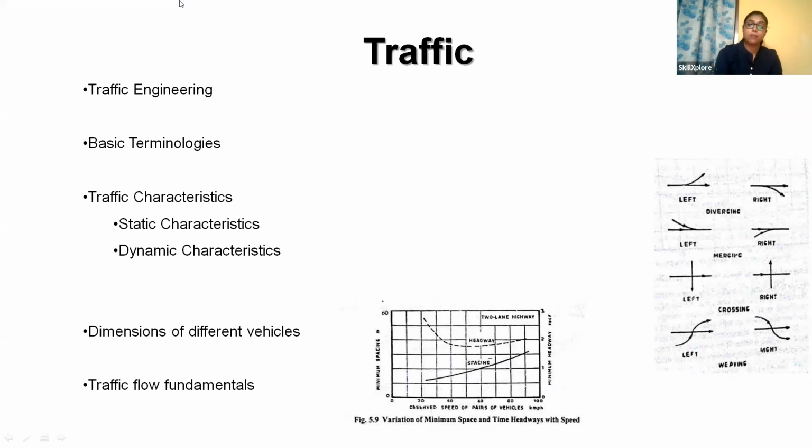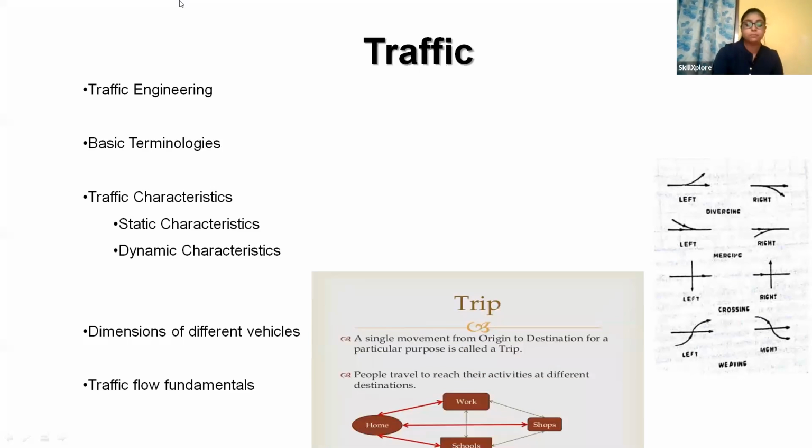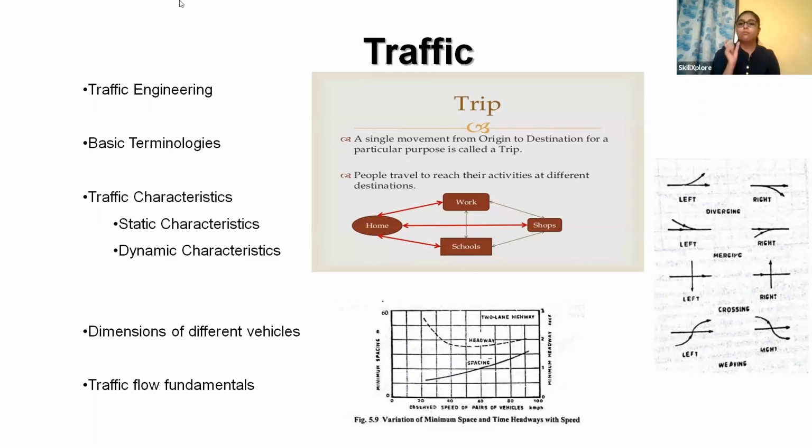But what is practical capacity? Again, it is not possible capacity. Practical capacity is different. It is the maximum number of vehicles that can pass a given point on a lane or roadway during 1 hour without traffic density being so great as to cause unreasonable delay, hazard, or restriction to the driver's freedom to maneuver under the prevailing roadway and traffic conditions. So this is actually the most practical way to put the capacity. Mostly, while we design a highway, we consider the practical capacity. So for one single term, capacity, there are this many subdivisions.